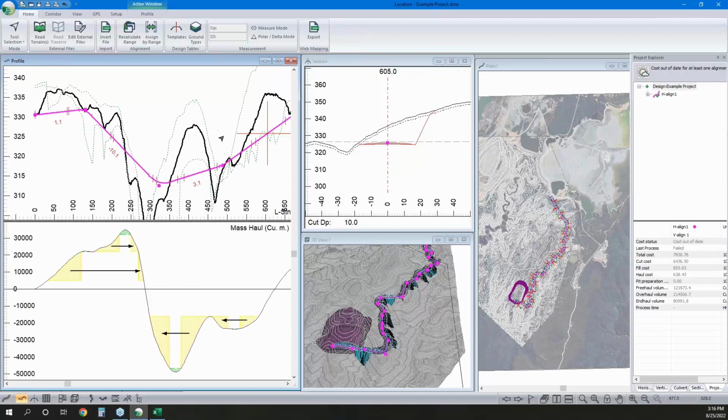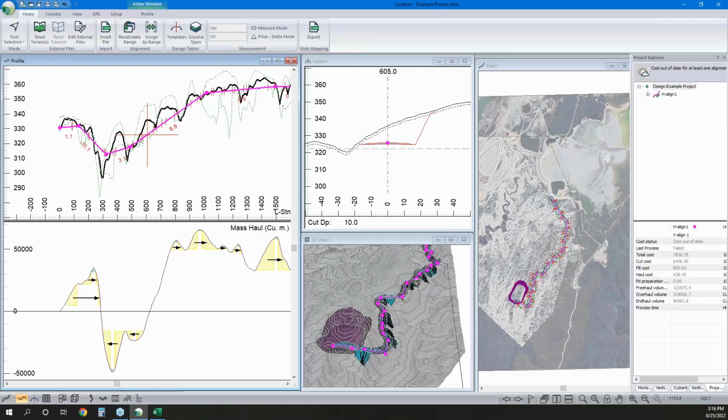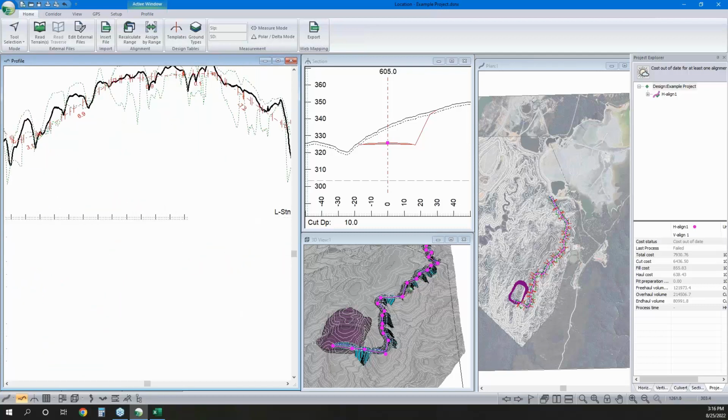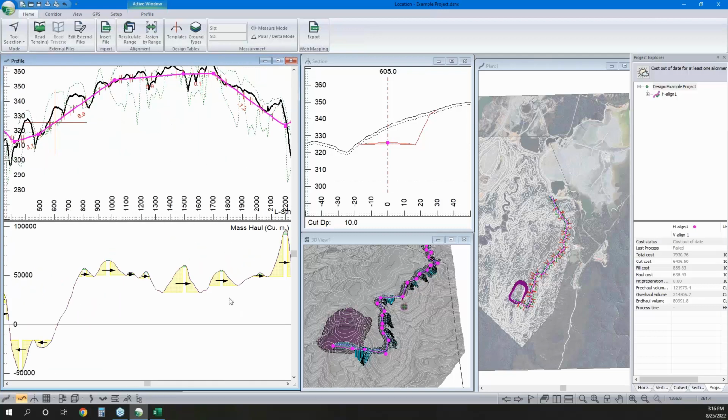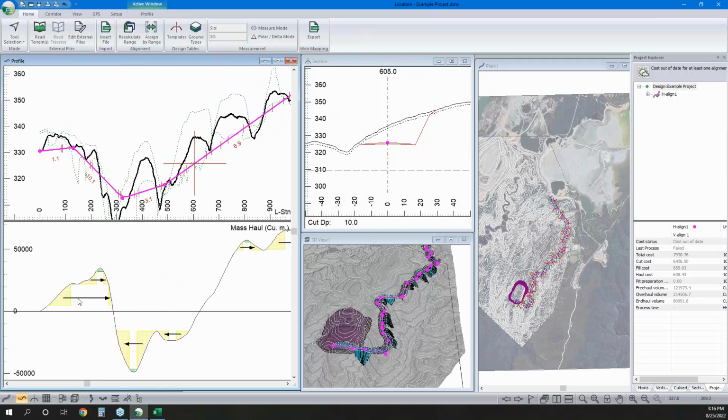And then the material volume that lands outside of the green and yellow is that, well, it's too far to push with the 250 in this case represents my dozer push. Too far to push with the dozer, so we're going to load it in a truck and move it that way. Now, with this, we can see that there's some arrows being indicated here as well.